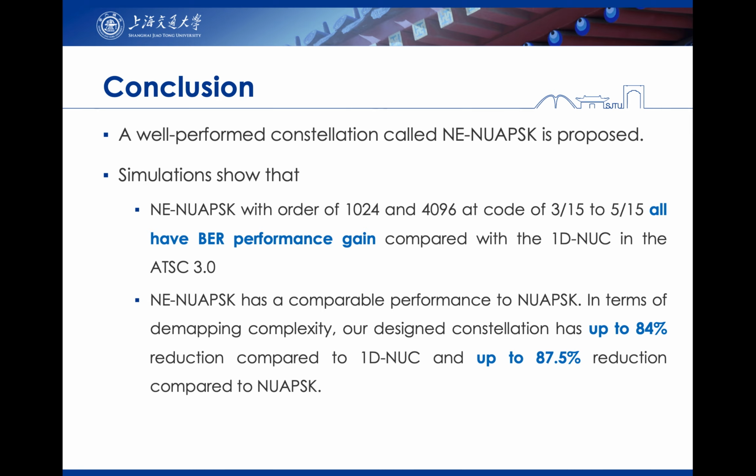In terms of demapping complexity, our designed constellation has up to 84% reduction compared to 1D NUC and up to 87.5% reduction compared to NU-APSK.